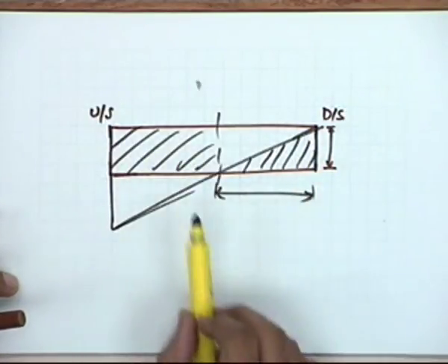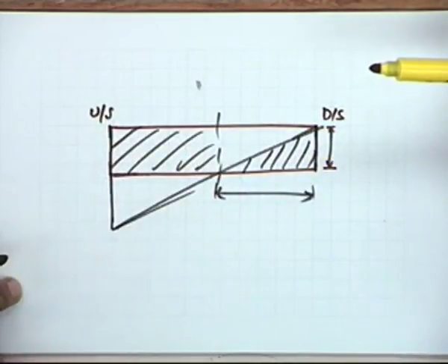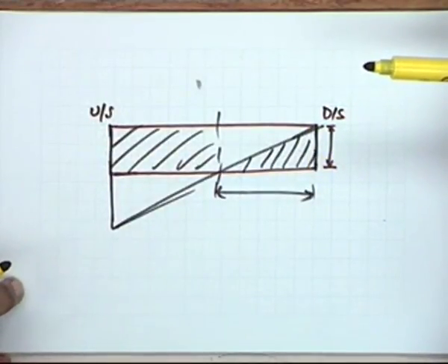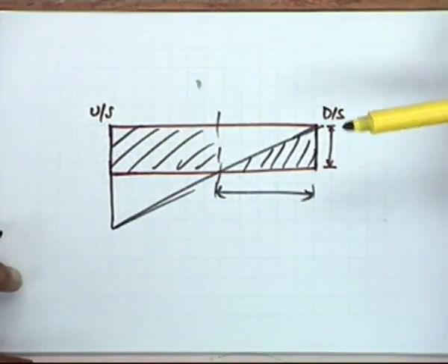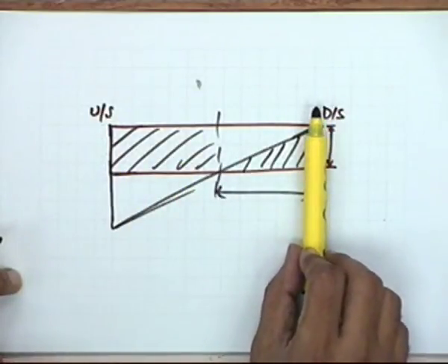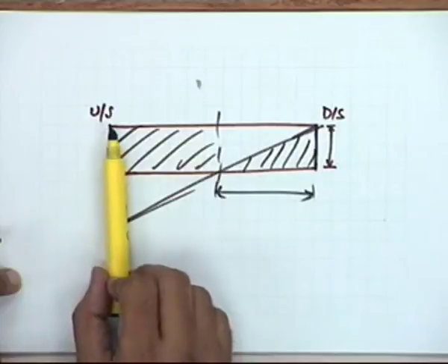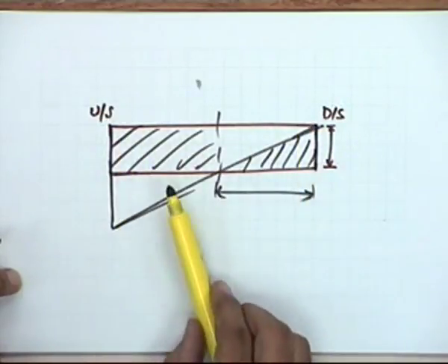So if you look at the efficiency defining that segment, the application efficiency, it will be very close to 100%, which is very good, because you are looking only at the volume. But in fact you are not doing the right thing, because the deficit has not been taken care of uniformly throughout the field.